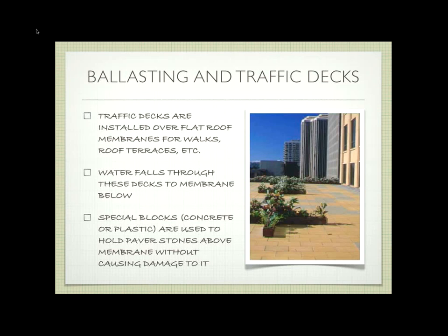Well, if it's a roof deck, you have to think about how you treat the roofing surface itself, because you've got that membrane that you can't have somebody walk out in high heels and punch a hole through, right? You need to be careful of that sort of thing, so you need something that somebody can walk on that's independent of the membrane itself. So a lot of times it's going to be some kind of special decking that goes on top of the roof membrane, that gives us that extra protection so that we don't cause damage.